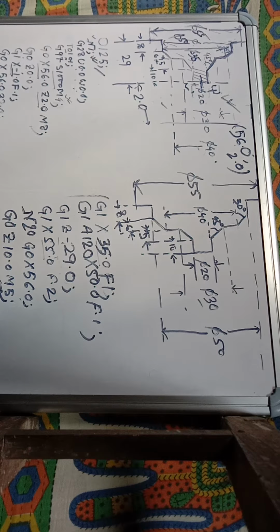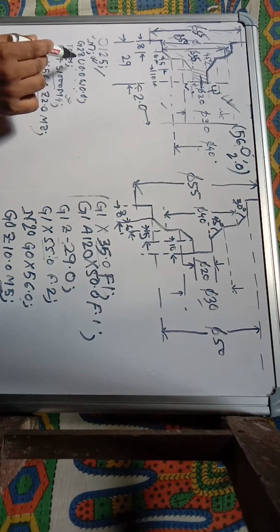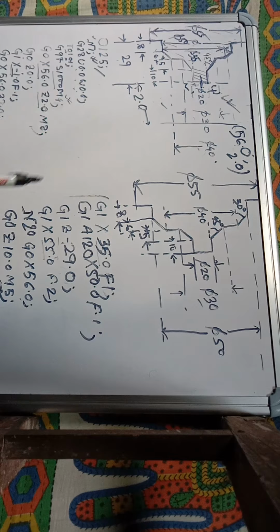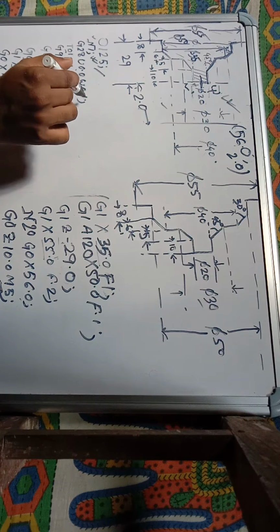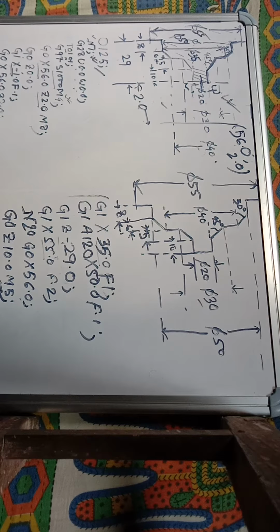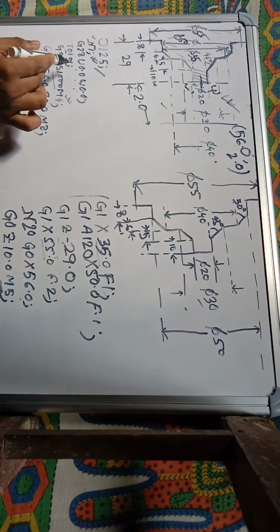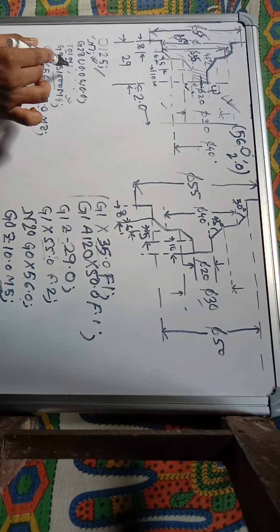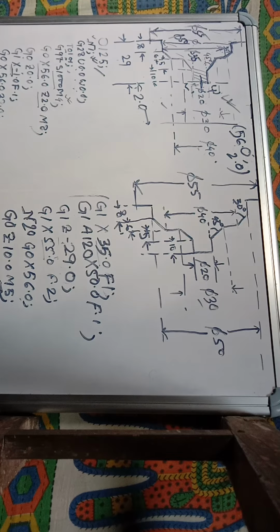What does it represent? The tool you will use for cutting is in home position. U0.0 is used for incremental, and W is also used for incremental. After that we use an end of block. Suppose you use tool number 1 and you have given the offset in tool number 1. So you have to call tool number 1, and this tool will help us cut this profile.